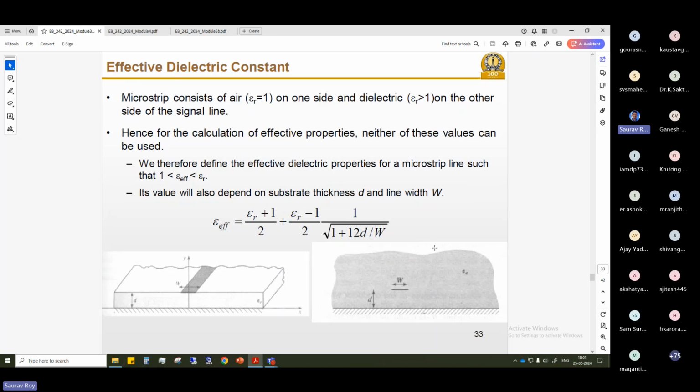So for the effective permittivity, you can substitute the normal dielectric as well as the air together as a combined dielectric with epsilon E. See, left is the actual substrate we have, and right is the substituted dielectric, which has a permittivity of epsilon E. This permittivity is given by a calculation you can find in the Pozar book or any book. It will have a thickness of D, and the combined permittivity will be calculated like that.